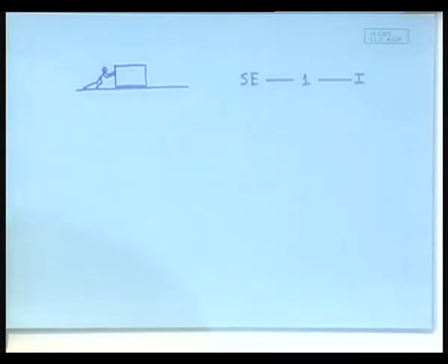Understood? So, whenever there is a force applied on a mass, by looking at the system's structure, you have to identify which elements share the same flow and connect them by the 1 junction. Now, what is the property of the 0 junction? They equalize the effort. What could be the mechanical representation of something that equalizes the effort?